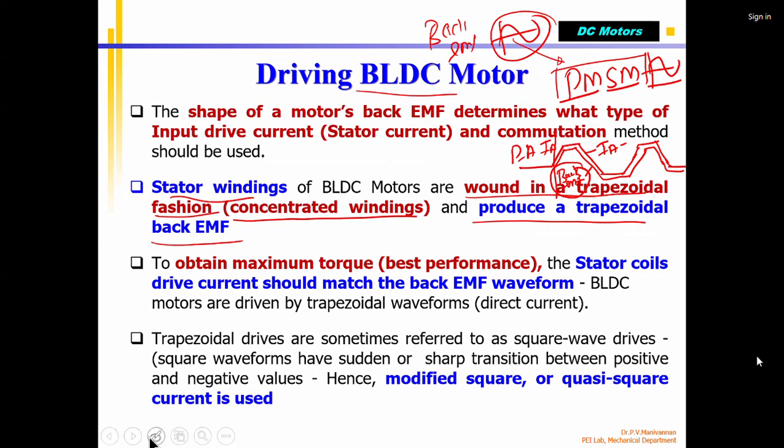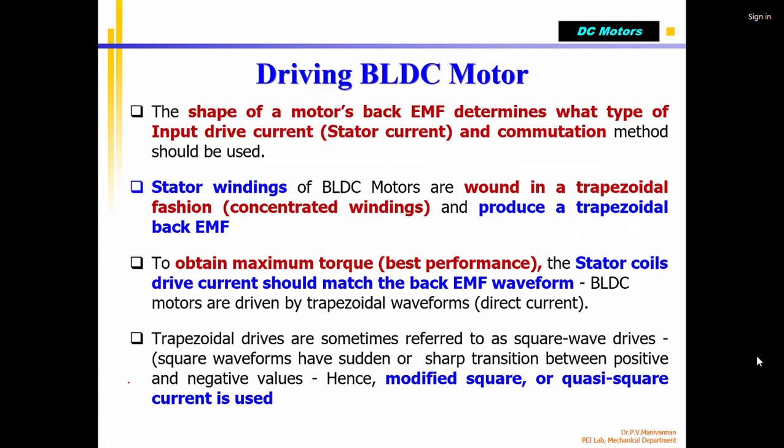Please note that in the case of the BLDC motor or permanent magnet synchronous motor, there is an applied voltage which is sinusoidal in nature, so the current is sinusoidal. The back EMF is generated due to the rotor magnet, because the rotor is rotating and works as a generator. That will be another sine wave. So the difference in voltage is called the driving voltage. Correct? The back EMF is always negative compared to the applied voltage.